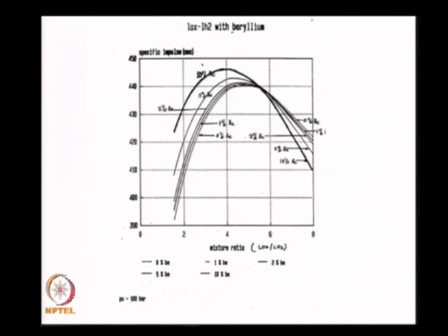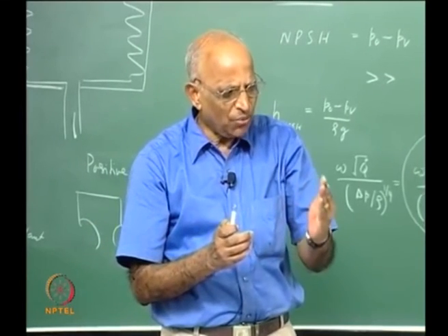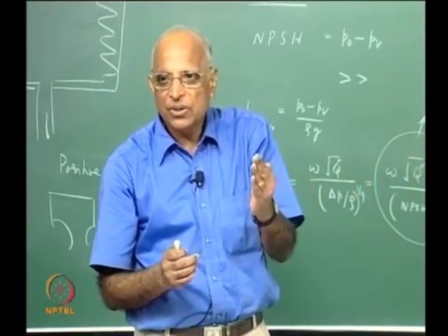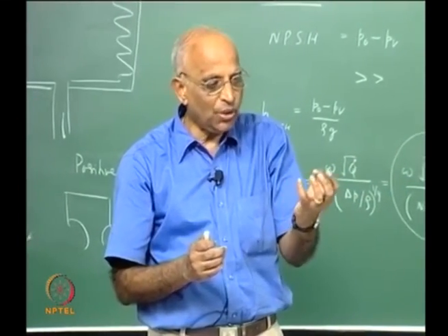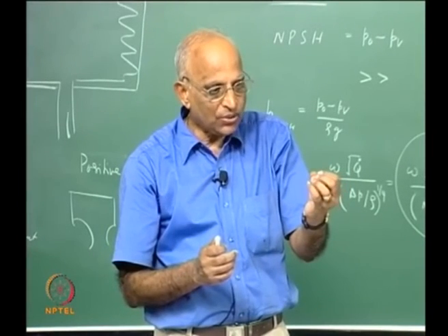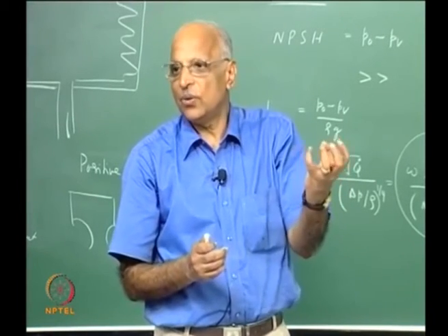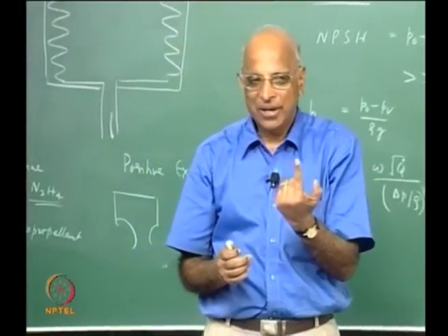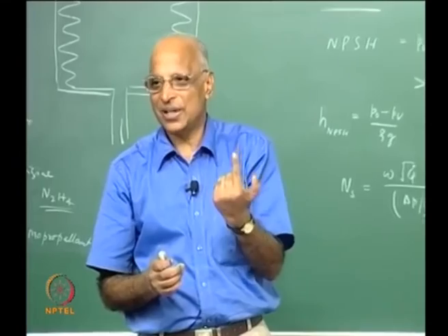The point one is higher molecular weight of the exhaust. Second is that metals require some more time to burn, and sometimes the metal turns into an oxide, but unless that oxide releases the heat, I do not get the energy, and that is where I gave you that assignment, wherein with dissociation let us calculate the products of combustion. It will illustrate the different types of problems we have.